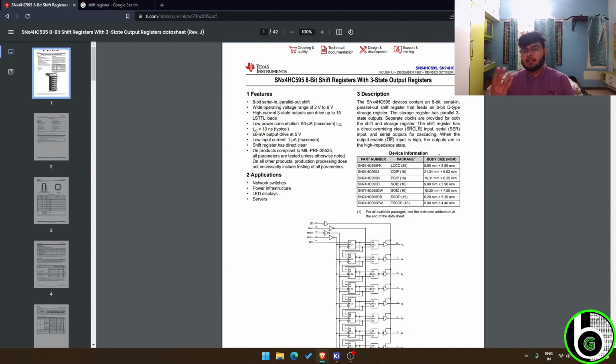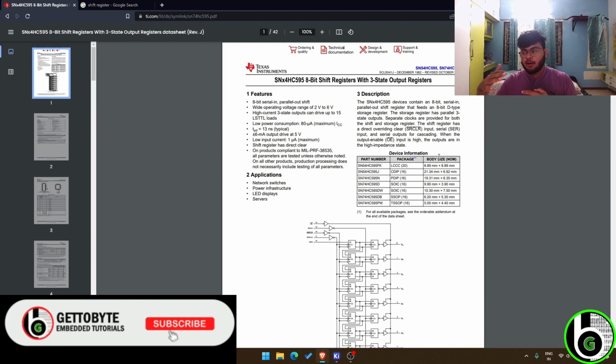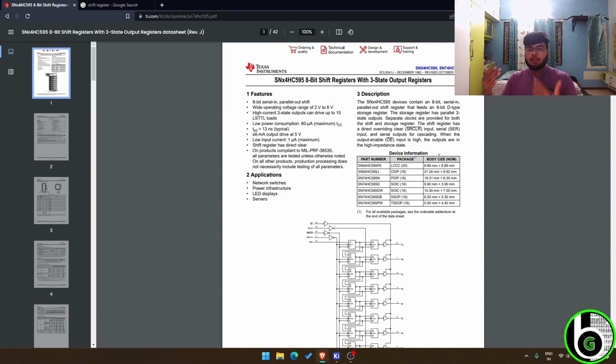That is, you could control say 8, 16, powers of 2 essentially. So what we do here in a shift register is we send on one of the 2 pins, that is the clock pin, a clock signal. It's a pulse train: high, low, high, low, high. And in parallel to that, we also send a signal of high, low, essentially telling which pin is supposed to be pulled up or pulled down.